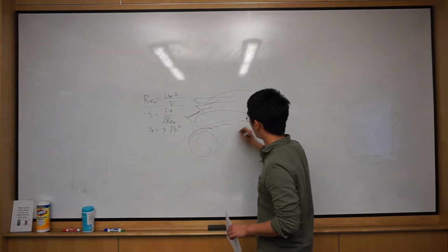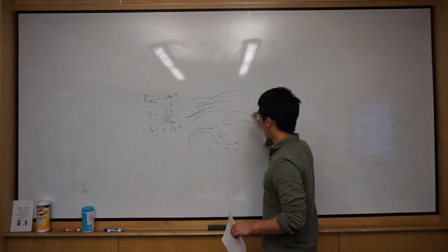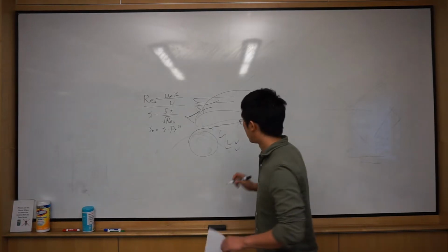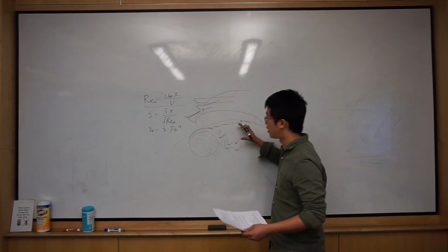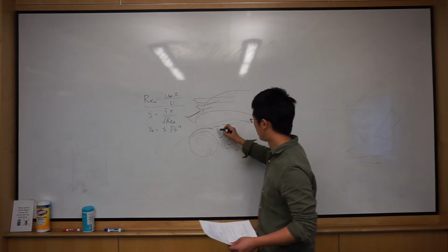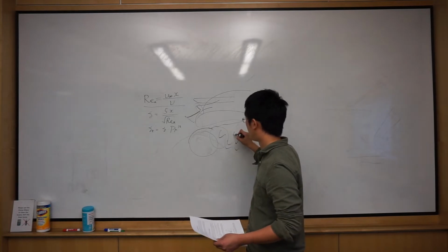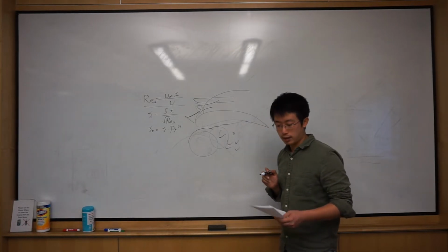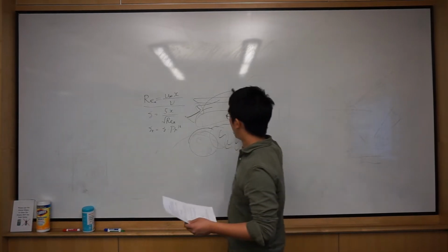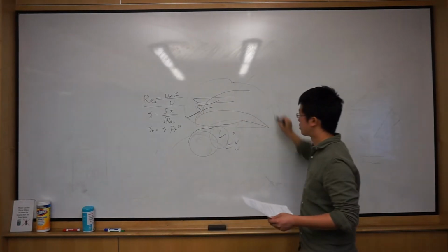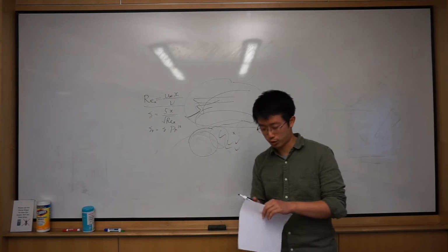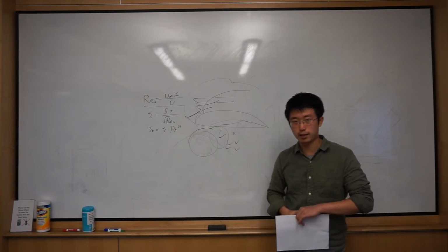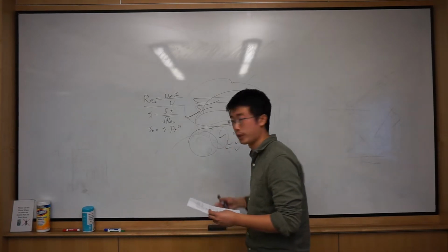Here it can separate, and here become a high pressure zone, and there's not enough mixing, and we have effectively a super thick boundary layer. So the heat transfer here will be very bad, right? And I think if you can comment on this part, it's good enough for us to give you full credit. If you know more, that's even better, but this is the full picture.